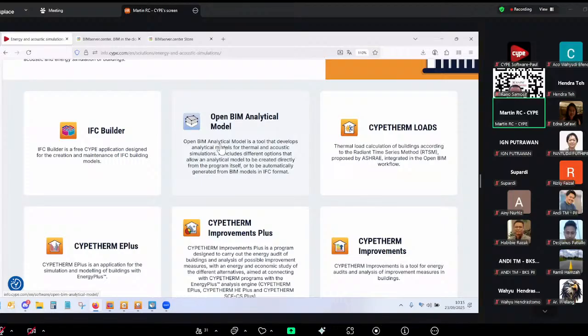So all that information is generated automatically by the IFC Builder. We have that opportunity, right? So we model in 2D floor by floor. We'll show you in the second part of the presentation, right? And you're generating a 3D model that you may generate floor by floor. And when you generate that model, it already contains the information about what I just explained. So by using this, we are saving steps if we are going to model with the aim of getting a professional energy analysis, right?